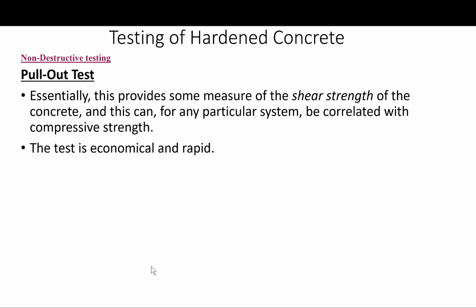So essentially, this provides some measure of the shear strength of concrete. And for any particular system, this can be correlated with compressive strength. The test is really economical and rapid, although it does leave a hole in the concrete that must be repaired, but this is really not a big deal. It is probably better than those discussed previously. So this is a good test because a greater depth and volume of concrete are tested in this case.